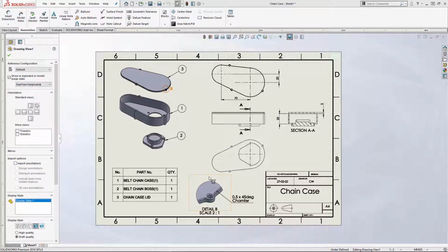So some of these things are specific to assembly drawings, some are more generic, just general drawing skills, and then we'll have a little look at editing the appearance of some of the annotations within the drawing. So when I say annotations, I mean everything that is text based. So all these dimensions are classed as annotations. Text can obviously include digits, so these have all got digits attached to them. The balloons are annotations, even down to things like the numbers or the letters assigned to the detail views or section views, or the arrowhead styles.